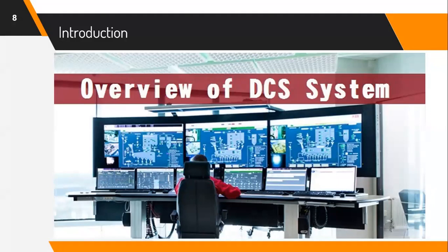Generally, the concept of automatic control includes accomplishing two major operations: the transmission of signals or the information flow back and forth, and the calculation of control actions or the decision making. Carrying out these operations in a real plant requires a set of hardware and instrumentation that serve as the platform for this task. DCS, or the Distributed Control System, is the most modern control platform. It stands as the infrastructure not only for all advanced control strategies, but also for the lowest control system. DCS plays a vital role in manufacturing industries as they are used to control and manage the processes. The networking capabilities of DCS are useful in process management, and the inputs or the resulting outputs can be analog signals or discrete signals.